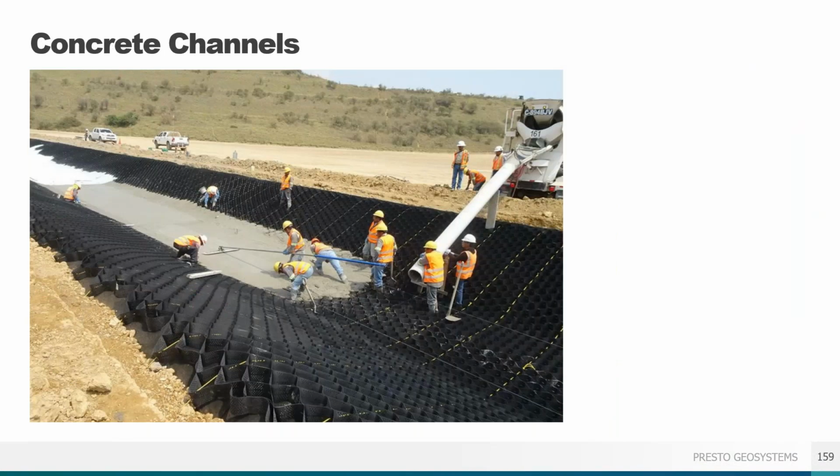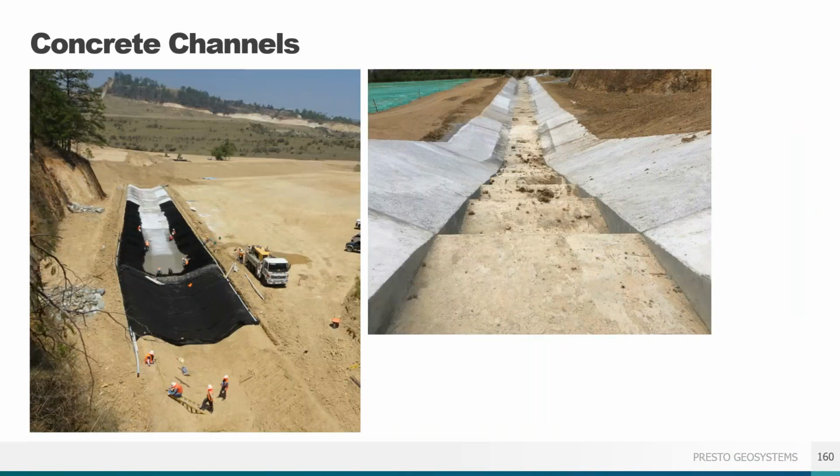If you have high flow or shear stresses for your channel armoring, you may likely be using concrete infill for your GEOWEB channel, like this mine closure channel in Guatemala. Here we see the technique tip of filling the channel bottom first, and then the side slopes. This is to ensure the system stays in place as no stakes are used, but also facilitates construction as crews can traverse the channel bottom as they finish the side slopes. Again, for the side slopes filled from crest to toe.